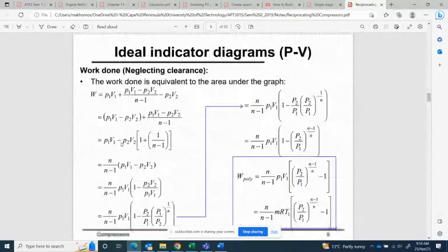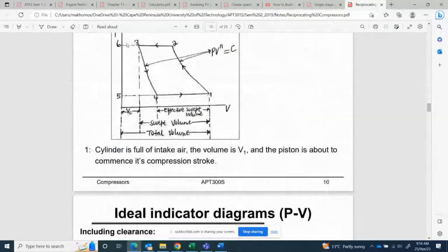Now, the space between 3 and 6, this is the movement of the valves. The valves open from that. So if we remove this 3 to 6, it means that the piston is going to collide with the valve when it pushes the air out. So it tells us that during that movement or delivery, not all of the air is going to leave the cylinder. There's a certain amount of air that will remain in the cylinder. That is at point number 3.